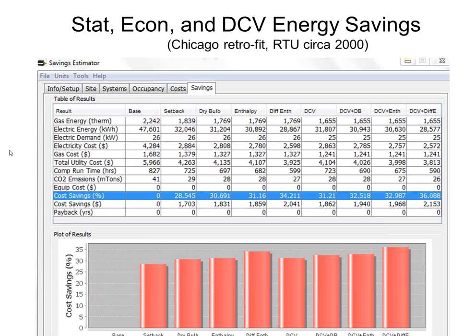Marty asks, how often, in my experience, do CO2 sensors need calibration? How many years do they last? I used to have to calibrate them, we tell everybody every year, but it was kind of like every 2 years was when they really kind of got done. But the new ones that we've had for the past 8-10 years, maybe even a little bit longer, the automatic calibration ones, like I said, we'd go check them, and typically they were within 50 parts per million, which is horseshoes and hand grenades close enough and within the specs of the original sensor, so we would leave them.